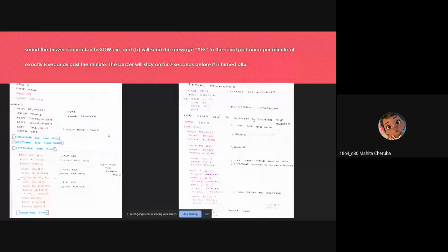So you have to write the code for turning on the RTC mode, then again for setting the timer mode, and then again the program for setting your time. After this, just as you set the time, you have to set the alarm time also. You can see the same steps repeating again and again. Only the register values will change, that is 1, 3, and 5.